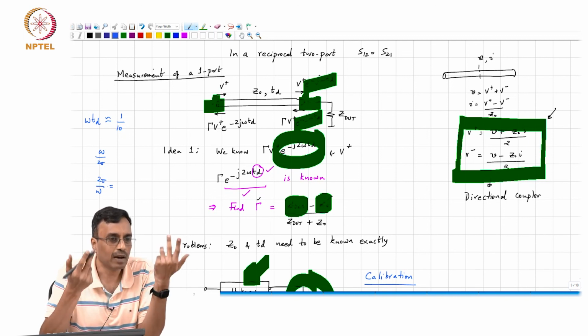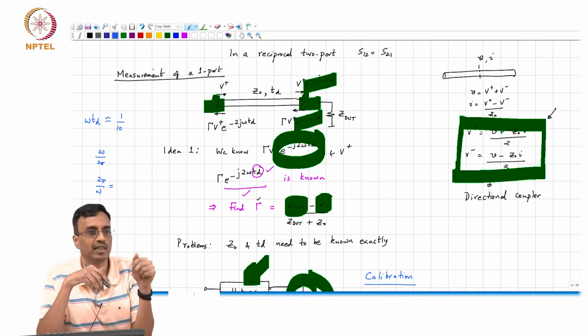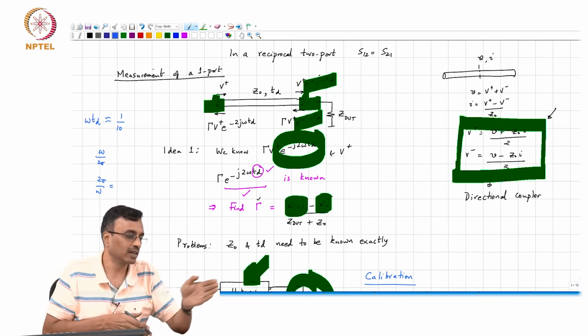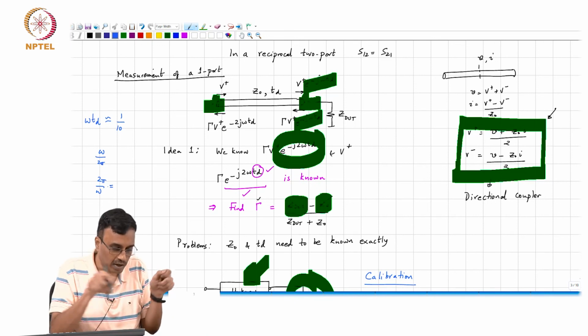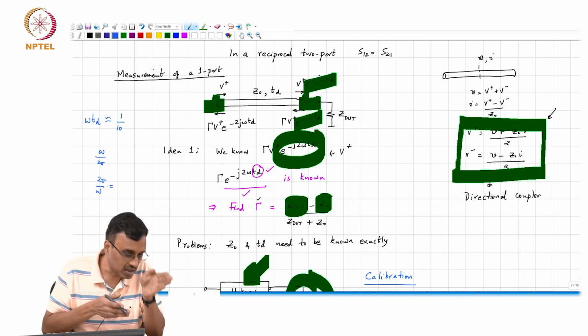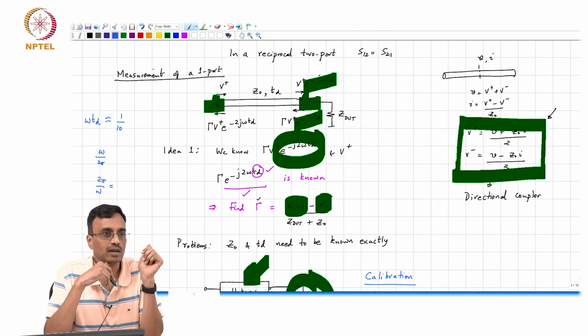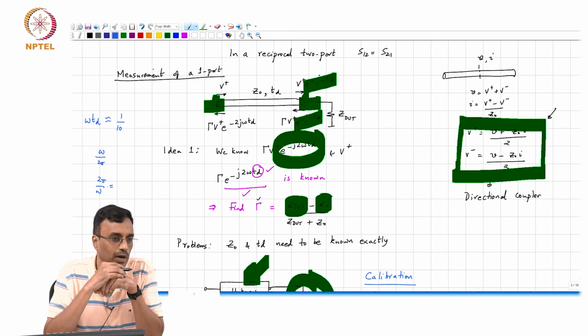The moment that happens, all distributed effects come in, and this notion of the voltage here, or saying I have shorted these two nodes together, does not make any sense, because the voltage here and the voltage here are different. Therefore, all these lumped element approximations become unworkable.